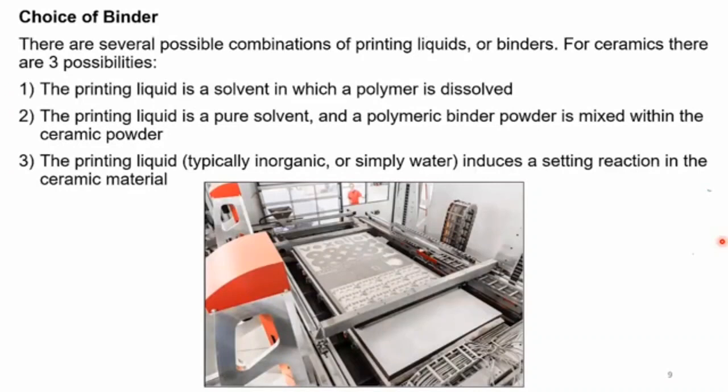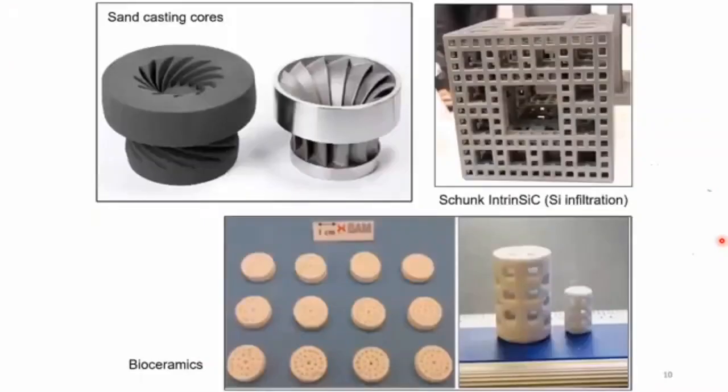material. For instance, we are working with geopolymers that are bicomponent materials. We have a solid part and a liquid part. The solid part is an aluminum silicate reactive powder, and the liquid part is an alkaline solution. So we are printing using this reactive liquid, and it works pretty well. You can see some examples of some casting cores made with this technology.